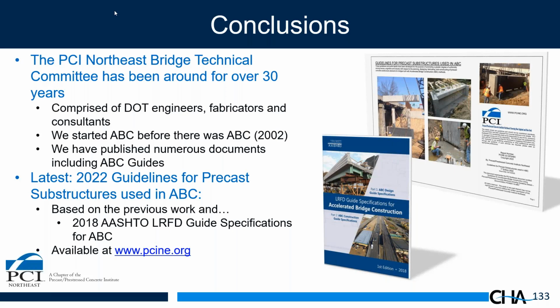Okay. We had a question that came in during the presentation. It's sort of a general question, but it says, are there any issues with precast fabricators developing forms? They're interested in reusing them on other projects without getting into too many custom forms for just one project. Yeah, well, you'll notice a lot of the details have simple rectangular elements. We do that quite on purpose. The reality is, in most cases, the fabricators are going to use wood forms unless it's a large project where they're going to have a lot of repetition.